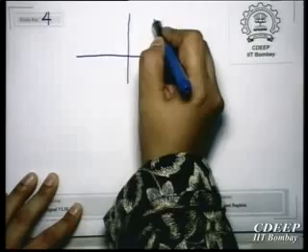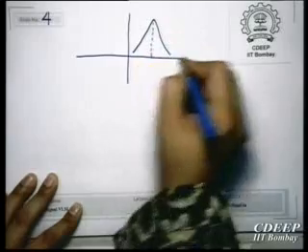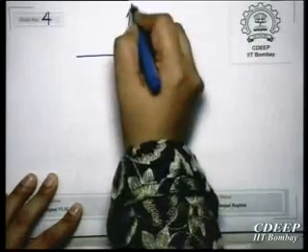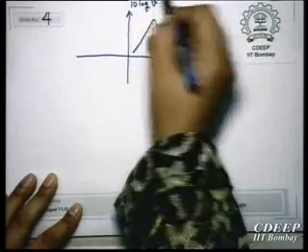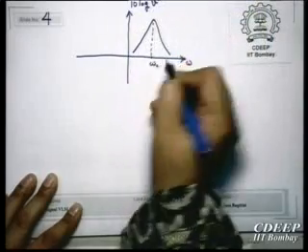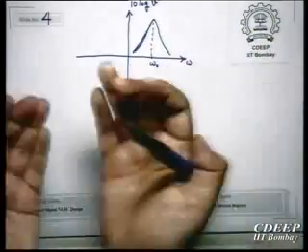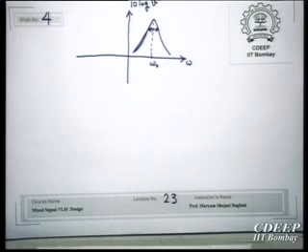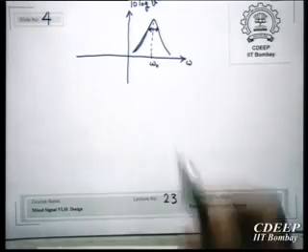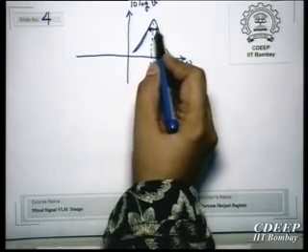If you look at the power distribution, for example, it will be like this. So this is the main frequency, and then here you will see a spectrum. If this is narrower, then your phase noise is less. This is noise. It may be deterministic, but effectively due to different random noise sources in the circuit, this bandwidth has an RMS value, an effective value.